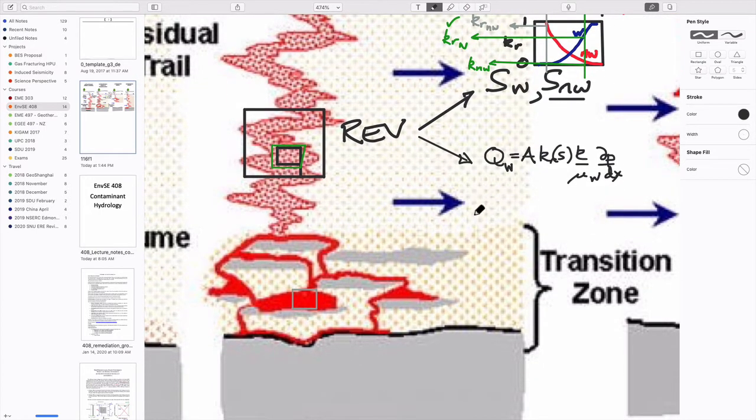And so if we know exactly what the volumetric flow rate is, we can also calculate what the mass removal rate would be. It would just be equal to the volumetric flow rate multiplied by the concentration, which we haven't talked about yet, but it will be that. And concentration, we made the point, is in units of mass per unit volume. And so the product of volume per unit time times mass per unit volume is mass per unit time, m dot, in other words. And so that's kind of simplifying everything we've done so far, really. That's kind of what we're aiming to do.